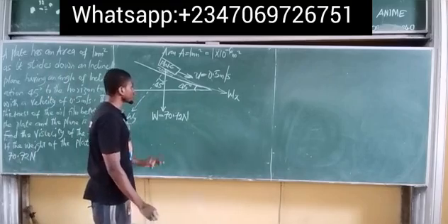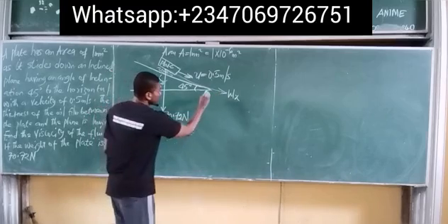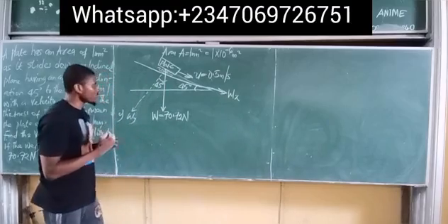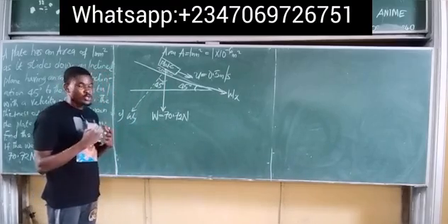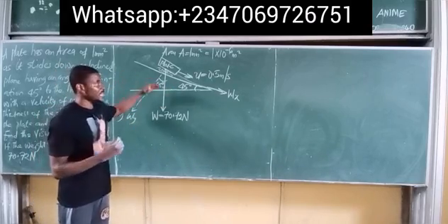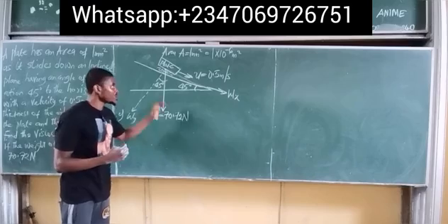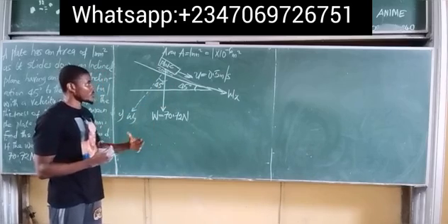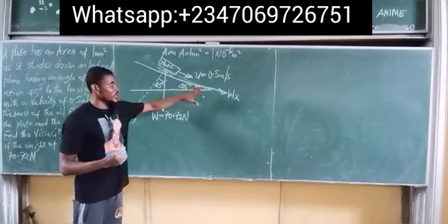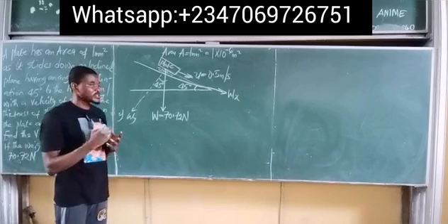All right, so we now need to resolve this weight to be inclined in the horizontal axis. Now take note, we don't resolve this weight to be inclined vertically because motion on the plane is not vertical. Motion is down the plane. So we only need the component down the plane. That's all we need. So we need to resolve this weight down the plane. And I always say, to resolve a force to any component, hold the tip of the arrow of the force, pull it to meet the component line. If it passes through the given angle, multiply by cosine of the angle it passes through.